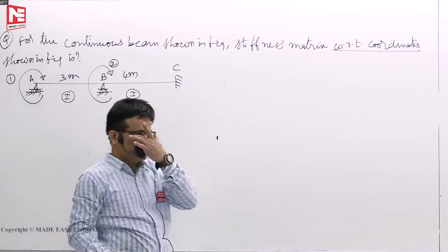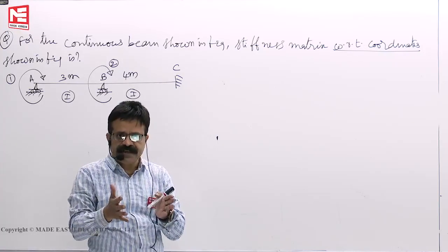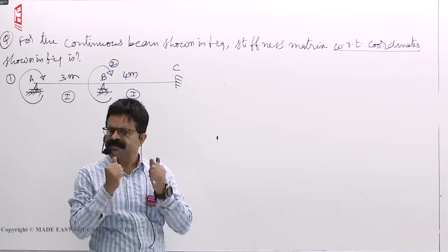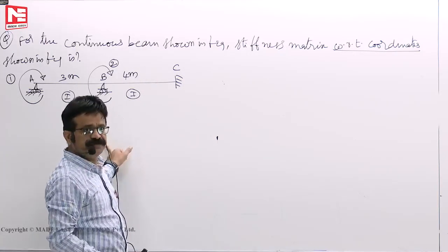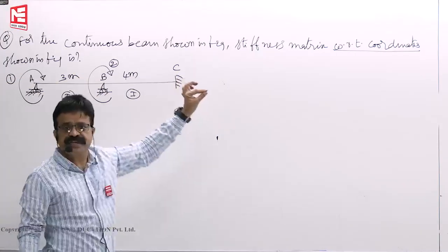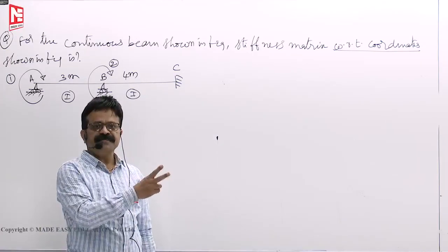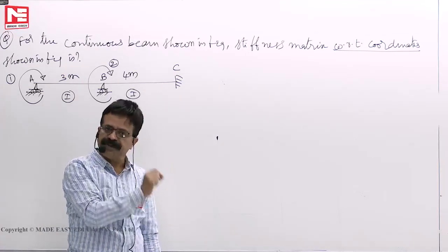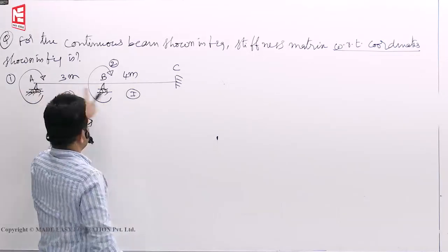In beams and frames, generally axial forces and the corresponding axial deformations are very small, so you can take them as axially rigid. If at all they give coordinate 3, coordinate 4 say, then axial deformations also you have to consider. If they are not given, it means those displacements are impossible, so no coordinate number is given axially.